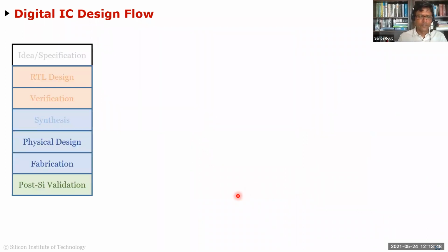All right. So now I'll show you the backend part of it. In the backend part, we are going to do physical design, which, like I said, if you're doing full custom, all it means is you're doing layout. You're just putting P cells and routing them. That's all. P cells are basically cells in which all the layers of the transistors are already drawn for you. You're just placing them and routing them.